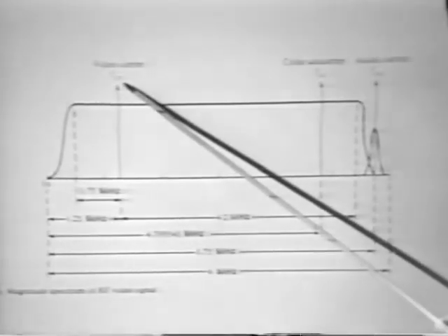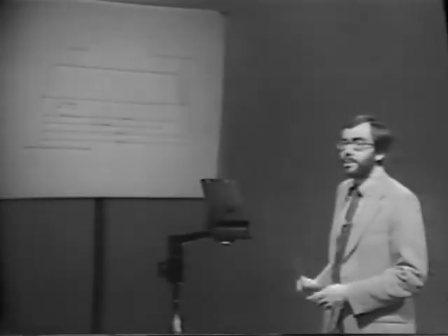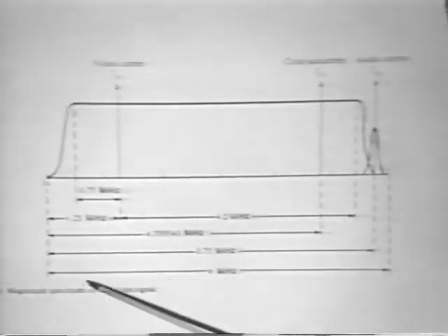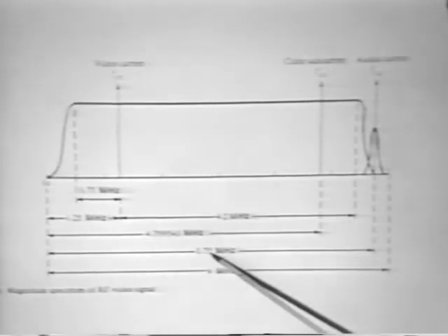We have here a video carrier, which we'll call F sub CV, and this is the carrier that was shown in the previous slide. It's that constant high-frequency sine wave upon which we impose the video signal. And if you recall when we talked about amplitude modulation, there are two side bands that are created with amplitude modulation. The spectrum is reproduced to the high end and to the low end of the carrier signal. And what's normally done in a video signal is to reproduce entirely the upper side band and to reproduce a little over 1 megahertz of the lower side band. This improves the fidelity of the system. And the result is that this spreads out over between 5 and 6 megahertz. This is the bandwidth of the video signal.